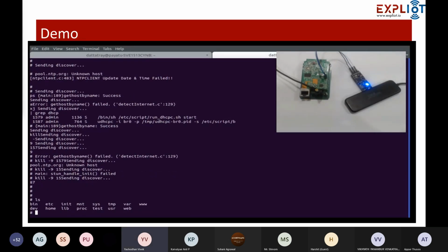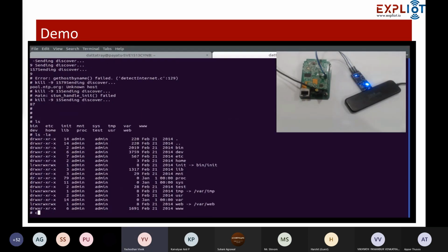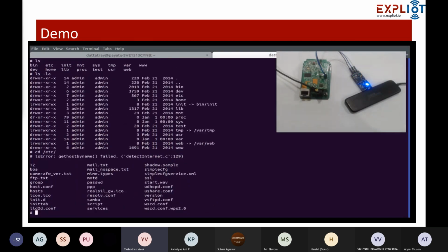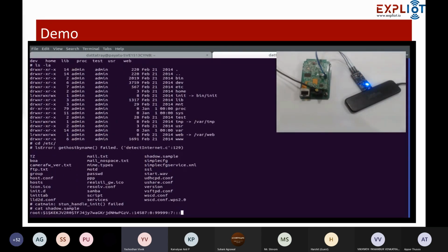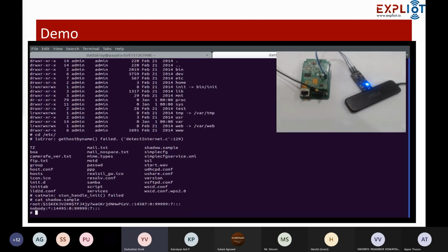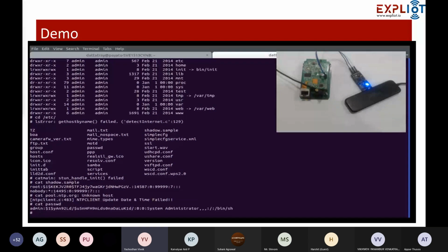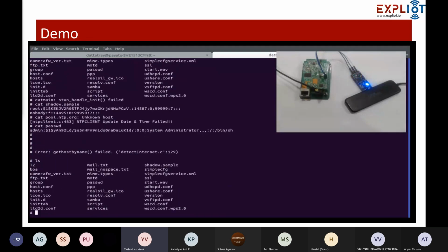Now, if you go into this file system, we want to find out where I can have credentials. In general, in a Linux file system, we have an etc folder where you are likely to find the credentials. So we have a system where, as you can observe, the cat password command shows a file with the username admin and a password for that. Okay. So this way, you can actually go and hack the IoT device from a hardware perspective.